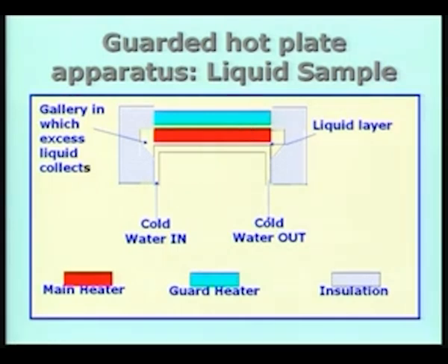So if the heat transfer is only from one direction, all the heat I am going to give to the main heater goes through the liquid sample, and if I take a very thin layer of the liquid as is shown here, I can assume one dimensional heat transfer through the liquid, and the same expression which we used earlier is going to be valid for this particular case also.